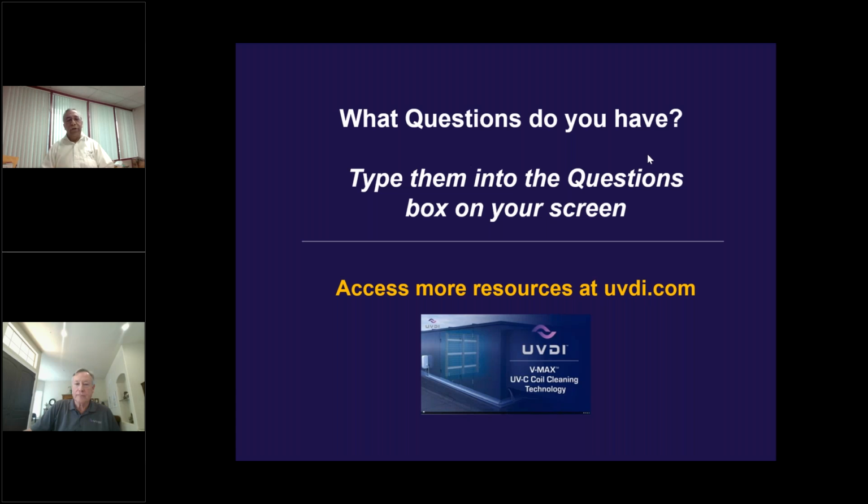There's a new technology which has come out called far UV technology, which has an output of 220 nanometers, and that has been shown to produce ozone. So UL 2998 would apply to that lamp. You have to make sure that any system which is using lamps below 240 nanometers should be tested to UL 2998 for ozone. But 254, not a concern. They don't produce ozone.